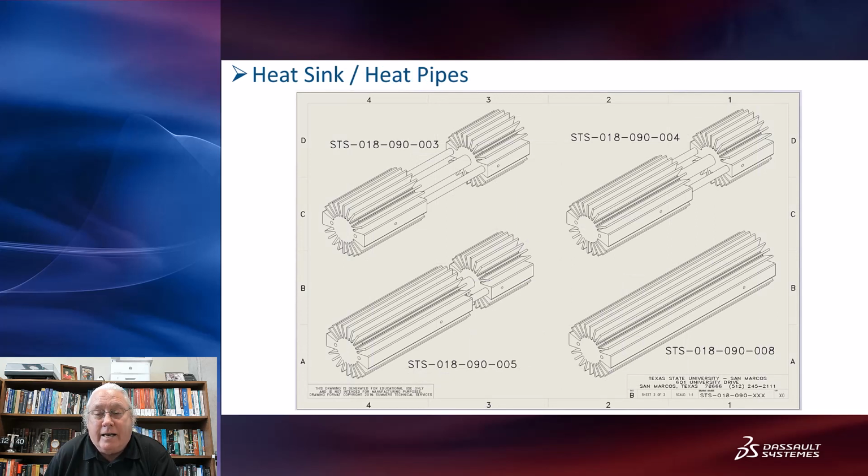So the hot side of the Peltier device would be bolted directly to this part of the heat sink. And the idea is you're trying to get the heat away from the hot side, and it's going through conduction through the back, through this aluminum heat sink. And there's air blowing around this in a contained cylinder here. So you're pulling the heat out through conduction and also through convection into the air.